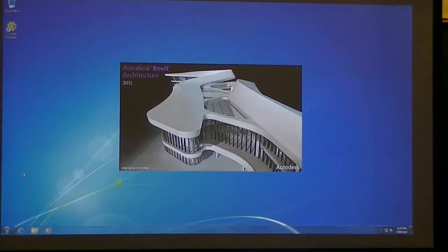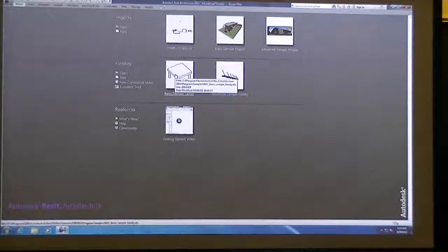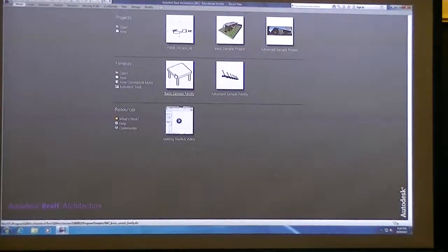Some of you have had questions about technical issues with your mass. We've started putting in interior rooms with walls that are straight up and down, but we've got curvy or sloping exterior walls associated with our mass. We need to find a way to trim these straight walls to the curvy or slanted walls. Revit doesn't like joining and trimming those types of situations, so I've got a workaround that will solve that problem.